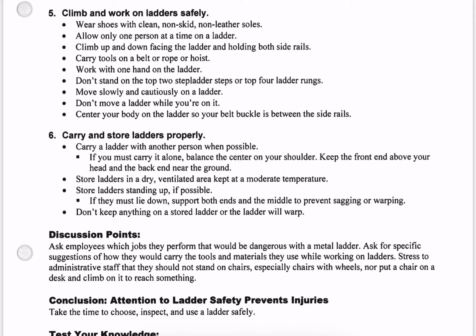Don't stand on the top 2 stepladder steps or top 4 ladder rungs. Move slowly and cautiously on a ladder. Don't move a ladder while you're on it. And center your body on the ladder so your belt buckle is in between the side rails.